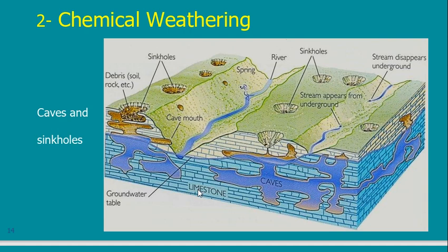So why is it important? Because if you go to any place and you start your site investigation and you find limestone, you have to anticipate that maybe in your borehole the limestone was intact. Imagine that you took a borehole here at the edge. It will be intact from top to bottom.